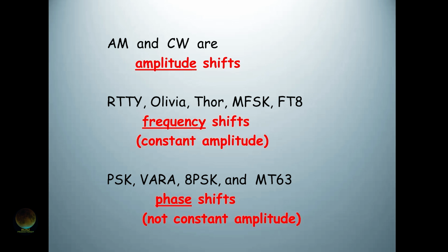RTTY, Olivia, THOR, they're all frequency shifts, whether it's 2 tones or 100 tones. They're just shifting the frequency. And PSK and Vera and these others, they're all phase shifts. But the phase shift modes also shift their amplitude, and I'll show you why they have to do that.